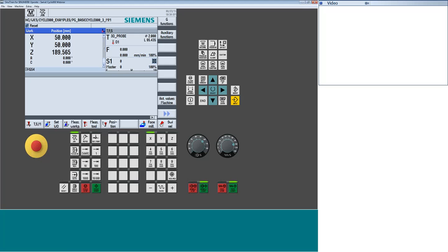So we're going to, that would be representing the screen that would be physically on the machine tool with all of the perimeter soft keys or software keys along the horizontal or the vertical spots. From there, we also have a basic representation of the machine's control panel. This is probably the thing that will vary the most from machine builder to machine builder. We have all sorts of different configurations of machine control panels. As well, builders can build their own, which is quite common in the industry.